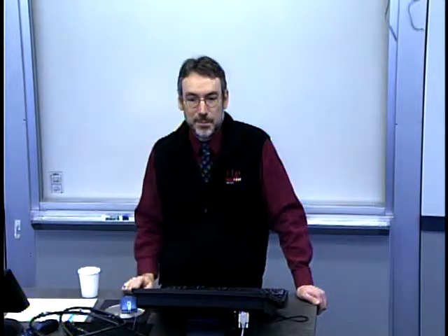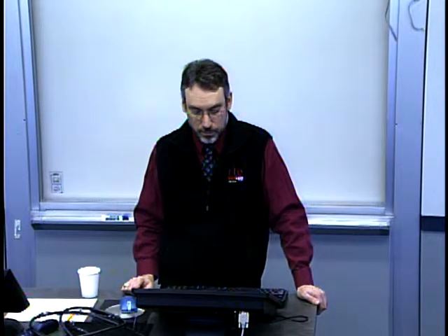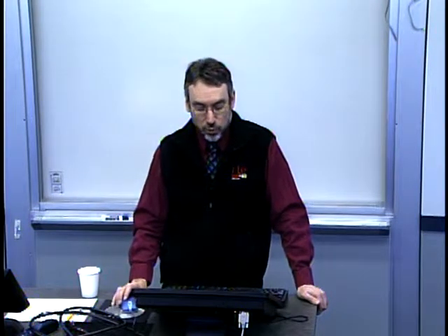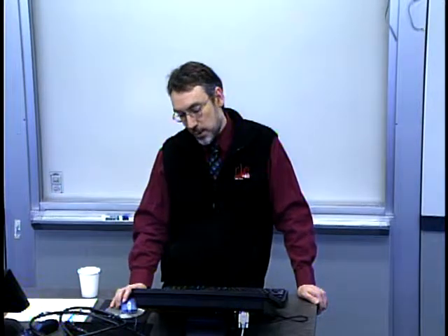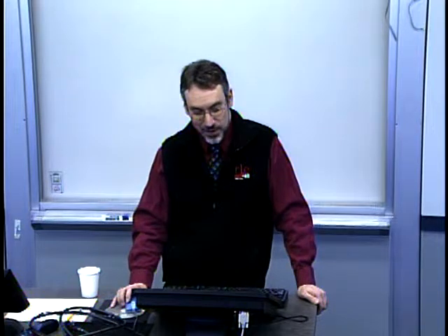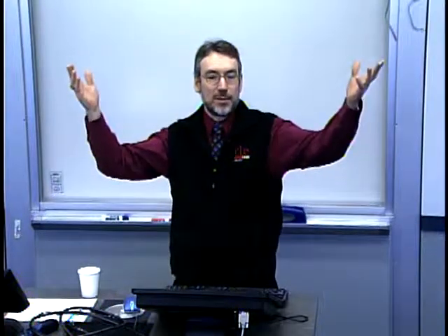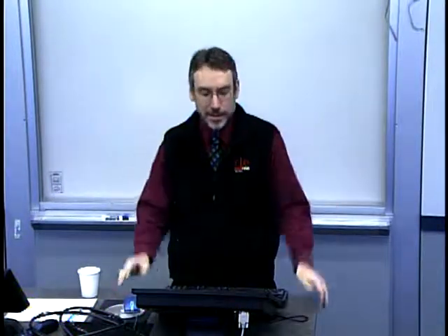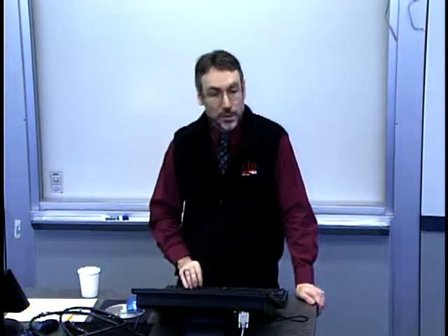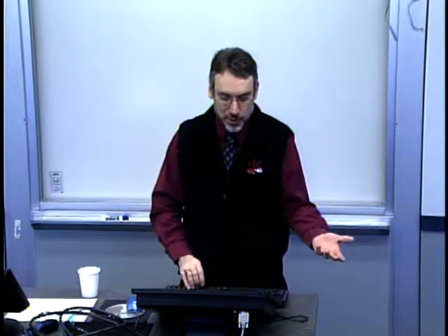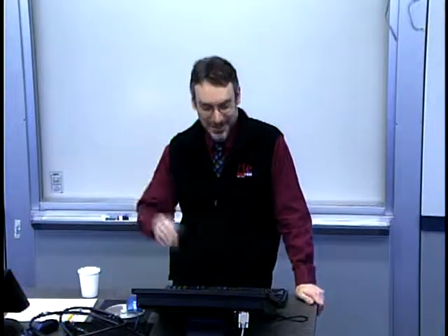Other ideas? Maybe there's a variation of time also, because of temperature variations over time. Right. So run number is a stand-in for time, and these are occurring. So your point here is, sure. Right. So it may not be equipment state, or indirectly, it may also be the rest of the facility environment or the line, and over time, who knows? Maybe this thing starts heating up, or the work pieces that are coming in have a different temperature. It's quite possible that there could be some other long-term state change.